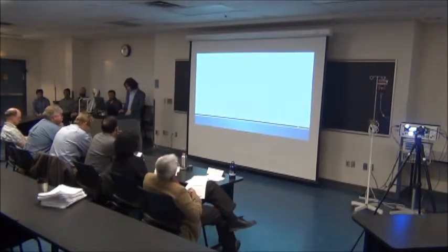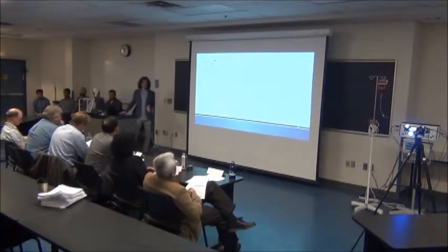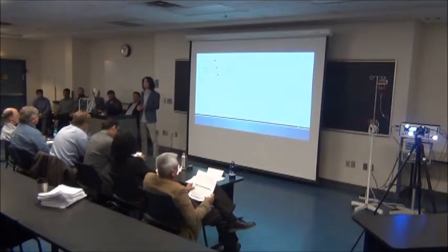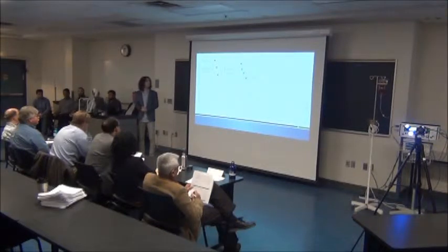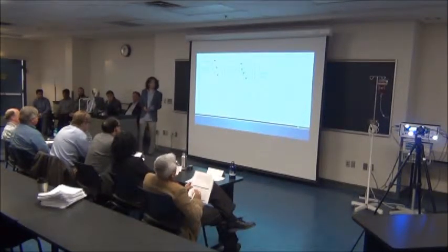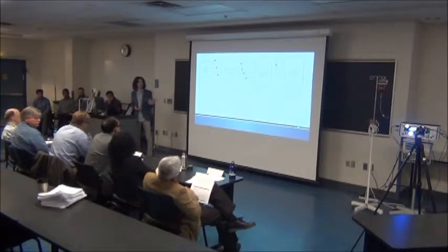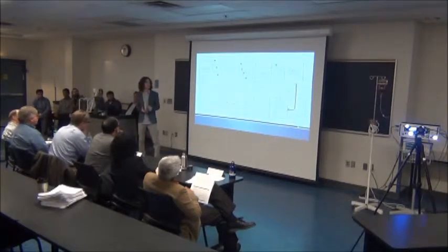Now we created a small animation to understand the theory behind the digital switch. What this digital switch does is take the signal, which is known, from the pots, from the voltage dividers, and pass it to the signal acquisition circuit. The first part is the counter, the 7490, which is a 4-bit counter, and we're using only 3 bits to make it count mod 5. We also have the decoder, and the decoder will decode the 3 bits and create the 5 bits. This decoder provides us with 5 different bits, and it will pick 1 bit at a time.